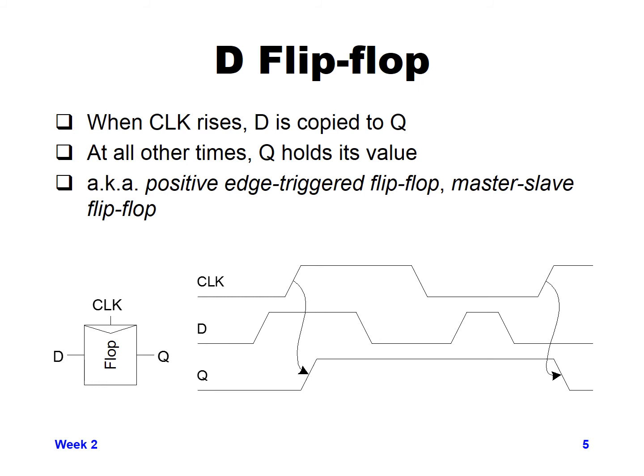We have a similar structure where we have two inputs. The D input is the main data that's going into the flop. The clock input is basically the control to the flop on whether you take the value of D or not. And the Q is the output. So in this case, rather than being level sensitive, where we let the value of D go through when clock is high or low, the functionality of a flop is that it's edge sensitive. And by edge, it's sensitive to the edge of the clock when the clock transitions.